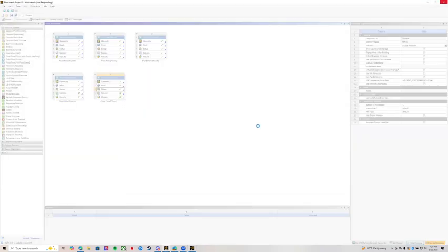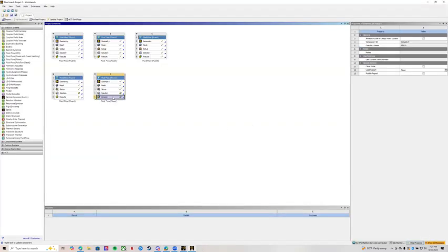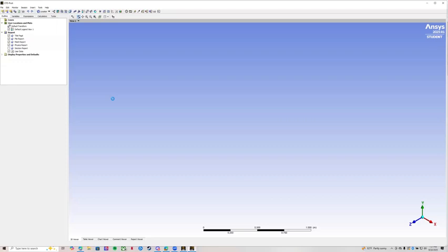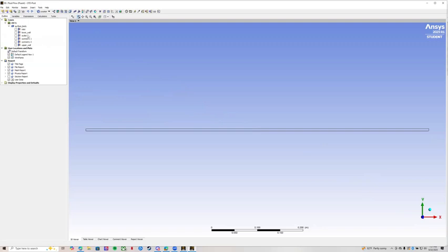Just gotta wait. Go ahead, click on here. Give it a second to update everything. There we go. So now we can go to our results section. All right, so we have our pipe. We're gonna go ahead and create our lines again. This time we're just gonna do a midline and end line, because the left line beforehand was just more of an example line to show a difference in flow. And then we're going to put that exactly at the halfway point, make it the same height as our pipe.